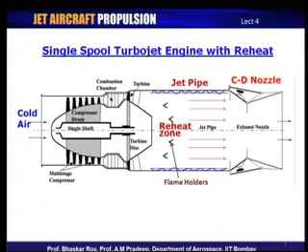Now, one of the reasons you have reheat is to raise the temperature or the energy of the gas to high values. And why do you raise the energy to high values? So that you can indeed get a high velocity jet through the nozzle. Now, when you try to do that, when you try to create a high velocity jet through this nozzle